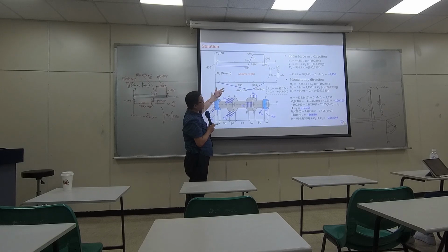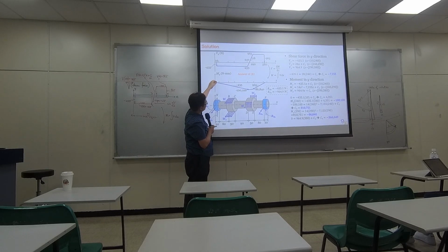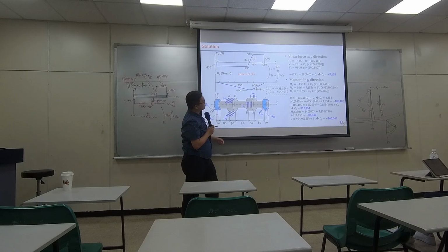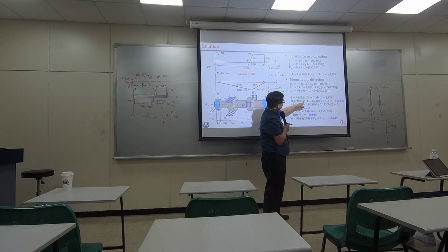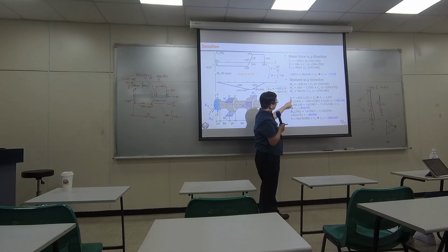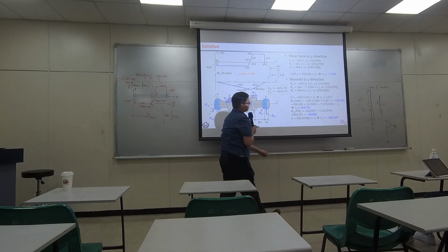Up to here, you started to have some bending. So that's the exact location where you have zero bending moment. And then when you start to walk toward the right, the bending moment starts to increase its value, either positive or negative. So you can use position 10 right here. At that particular place, the moment should be zero. So you plug into this equation, and you get the constant value right there.